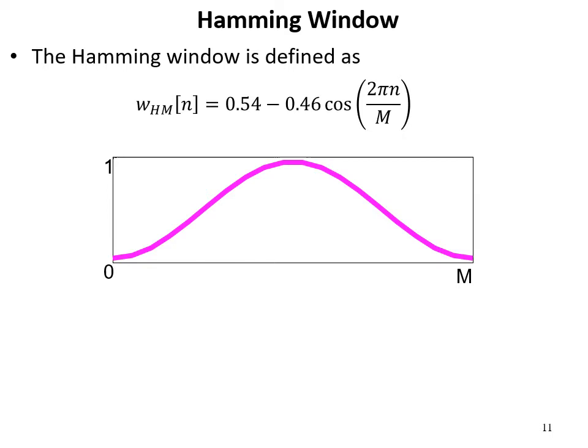we used the Hamming window for designing the same low pass filter. Right? So the Hamming window does not have a sharp discontinuity. It has smooth transition. Right? So it is from 0 to m equal to 0.54 minus 0.46 cos of 2 pi n upon m. In the last lecture, probably we had m minus 1 here for the same reason that we discussed in the previous slide. Right? So the Hamming window does not have a sharp discontinuity, and therefore we expect fewer ripples, but we should expect a wider transition band.